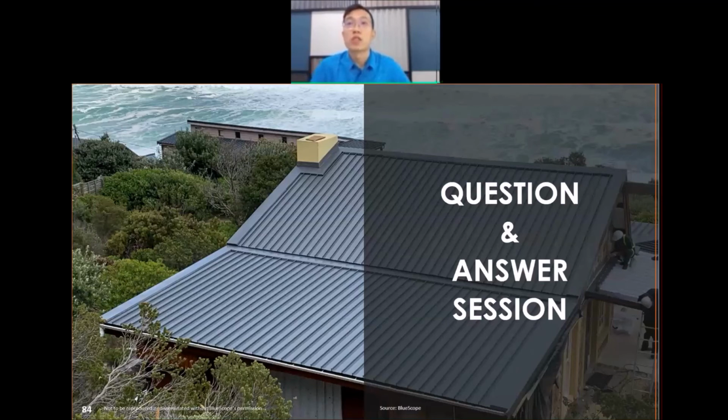So moving on to the next question. Normally, how soon will signs of premature corrosion occur at unwashed areas of cladding? What should we do if signs of corrosion occur? Okay, so again, the unwashed area I covered today was on the seawater side, where the sea breeze brings these salt particles and they accumulate on these areas. But in fact, it does not just occur near the sea, but is commonly seen also indoors, such as indoor pools and glove factories, where basically whatever is within the building is considered an unwashed area.